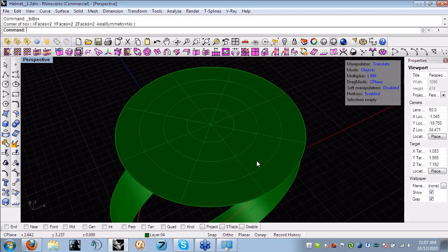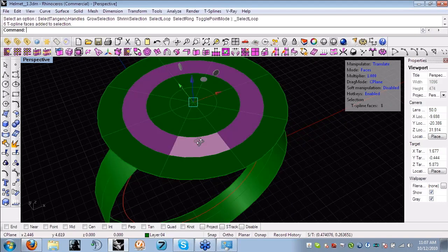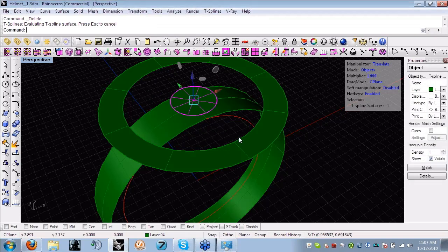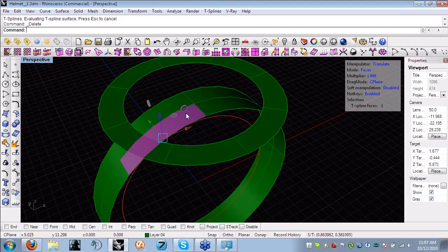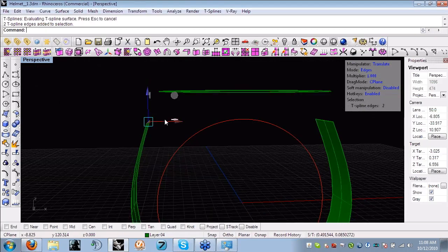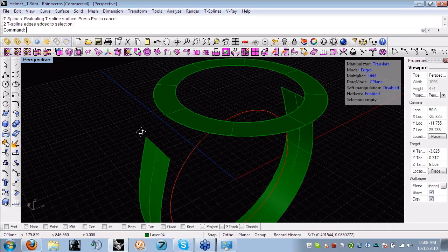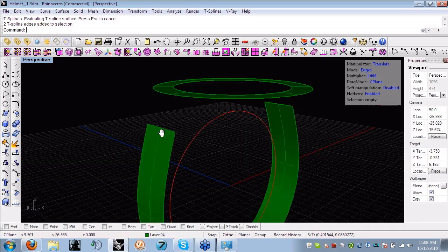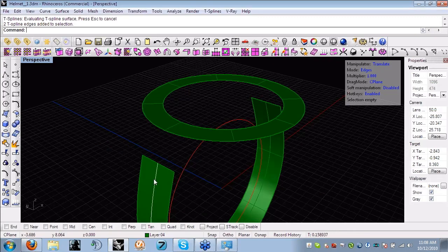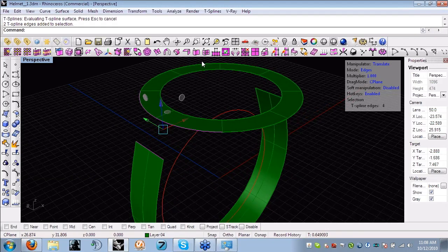That makes making this stuff real easy. So I just essentially grab that and throw it away. Just get rid of all this stuff here in the center that we don't need. And this is an easy way to make simple circles and stuff. You can do it with extruding a regular circle NURBS curve. But I like doing it with the primitives because I can visually see how many faces I'm going to get, so that I know that face lines all match up. So for when I do things like bridge, I can get them all together nice and easily.